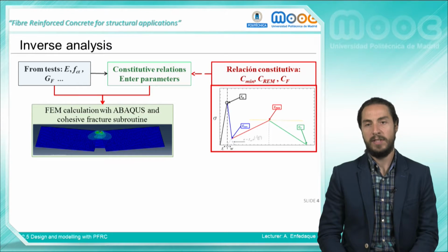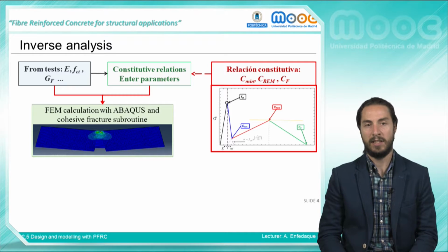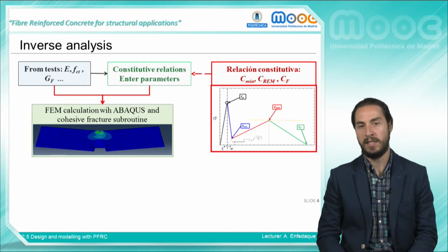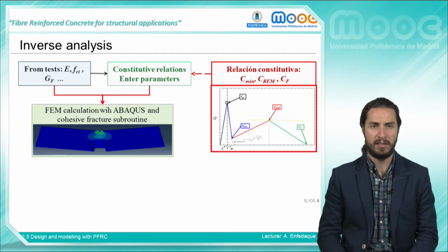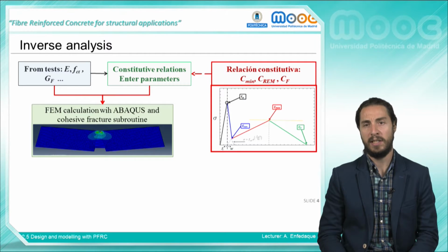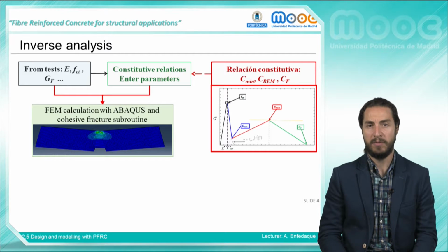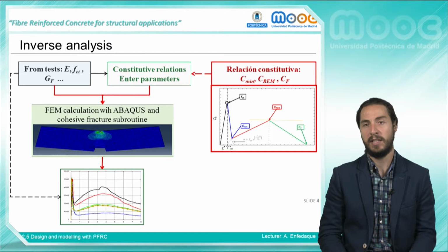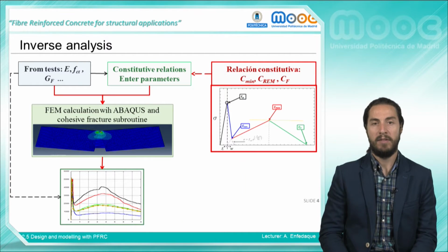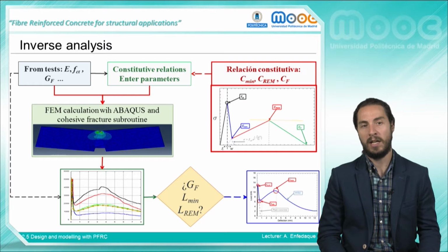The accuracy of this approach was proved by means of numerical simulations. Using the data extracted in the compressive strength test, the modulus of elasticity test, and the indirect test, and supposing a trilinear softening function, the complete behavior of the material could be checked. In order to perform this task, the material behavior was implemented in a commercial finite element software, using a user material subroutine. After the numerical calculation has been performed, the experimental behavior and the one obtained in the calculation were compared. If the fracture energy and the behavior are not comparable,